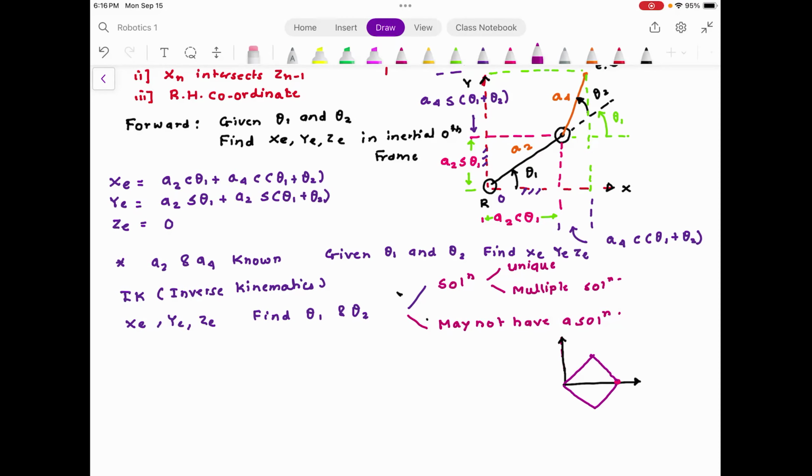Everyone understood this? Now, how do you choose which solution to pick? Today I will teach you how to solve inverse kinematics problems, but please try to understand, mathematically the solution that you would get from an inverse kinematics solver may or may not be practically realizable. As an example, Dobot Magician has some dead zone, because of the physical joint limits, it cannot get to certain angles.